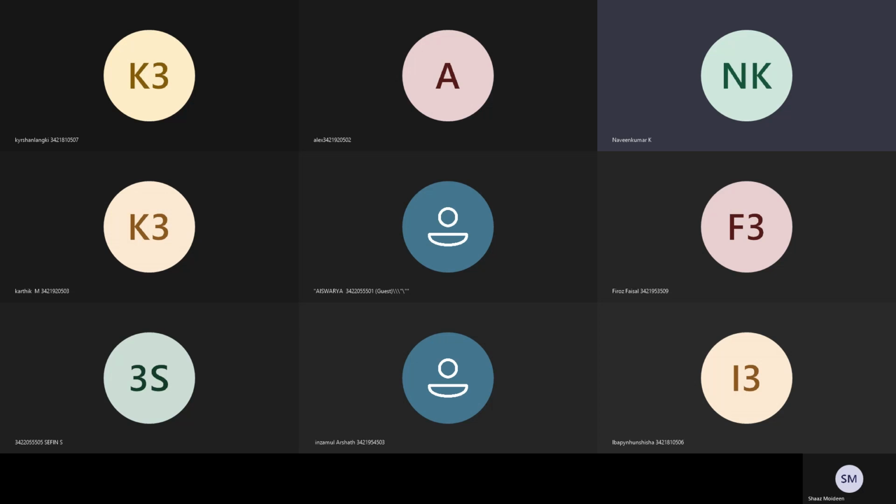Okay, so mostly the slabs on the bridges are of simply supported type. So you can either cast the slab in the site and place it as a simply supported slab, or else you can go for the precast construction.